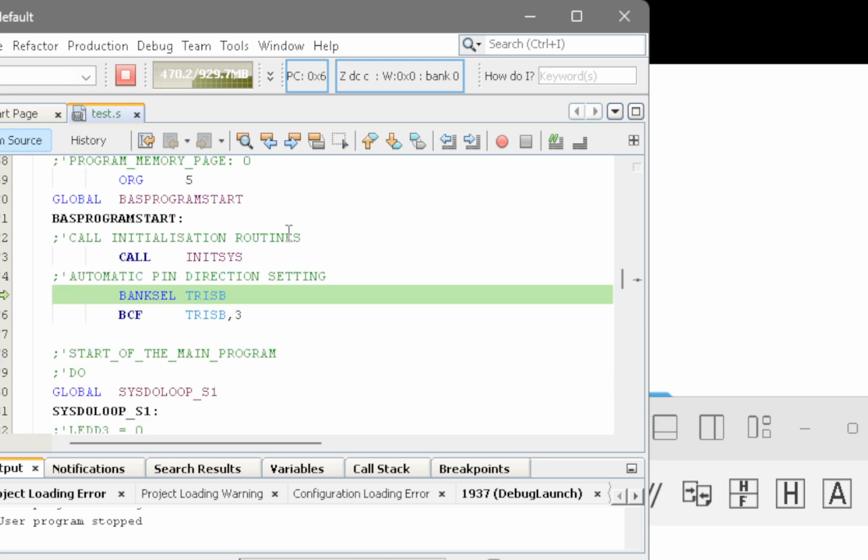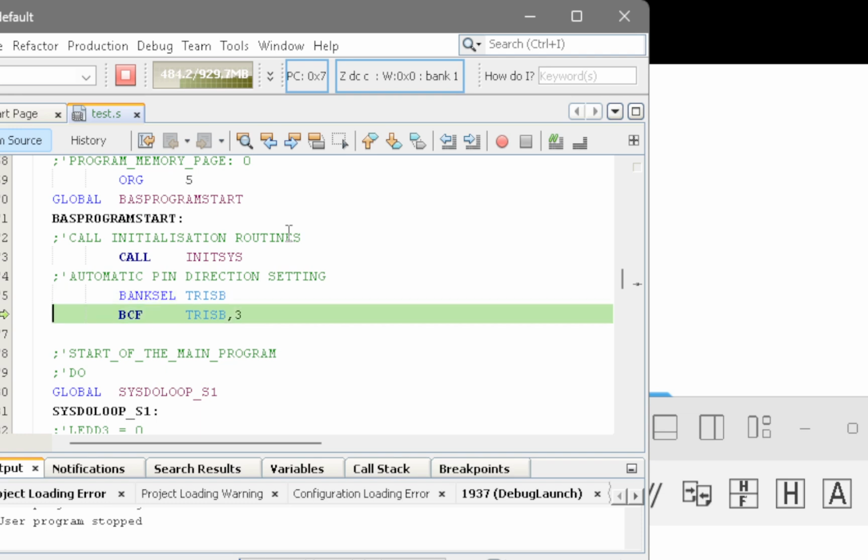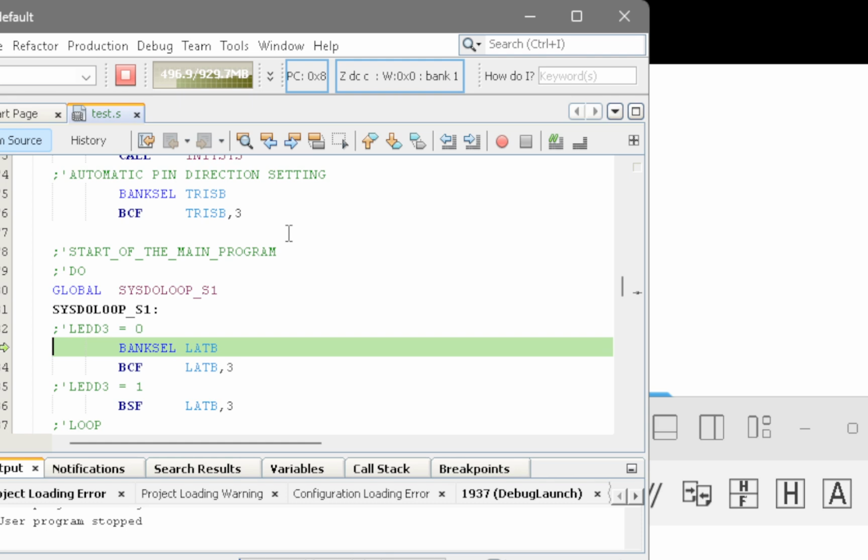Return. GCBASIC in this case, and I was unaware of this until I've just seen this code, has decided to automatically set the pin direction for the pin that we selected in our source program as an output. Did it automatically. I'm amazed at the way the compiler does things. So it sets up the automatic pin direction for you.